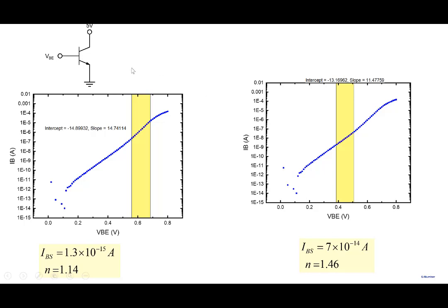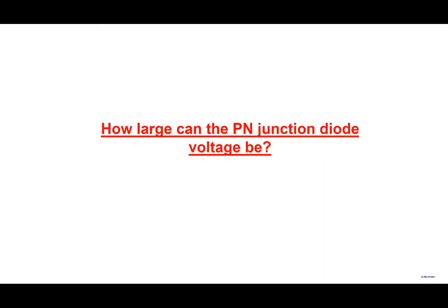What you are doing is applying this particular equation to the forward bias characteristics, and depending on different regions, you may get different values of IS. So do not confuse this with the reverse saturation current. If you really want it, you have to go and measure it. This is simply a current that you use to fit the forward characteristics. That's all.